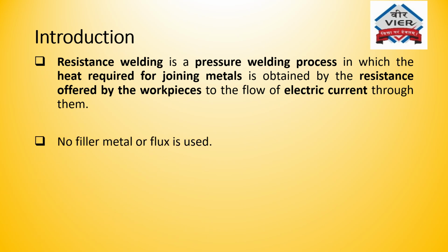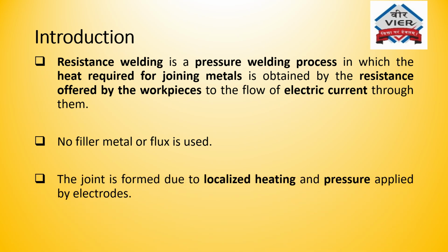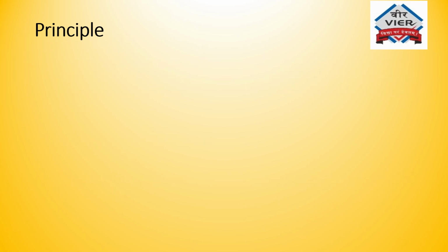In this welding process, no filler metal or flux is used. The joint is formed due to localized heating and pressure applied by electrodes. Let us first see the principle on which resistance welding works.